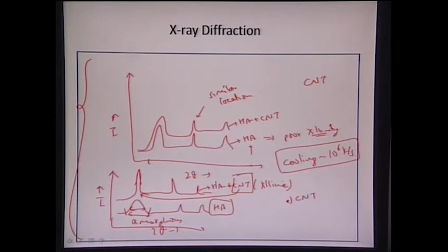CNT is responsible for inducing those crystalline peaks. And secondly, the CNT peaks are not really being observed out here. The crystallinity part is also being dominated by the carbon nanotube content. As we see, the processing can also induce some different peaks, which can be tricalcium phosphate, amorphous calcium phosphate, or even calcium oxide.